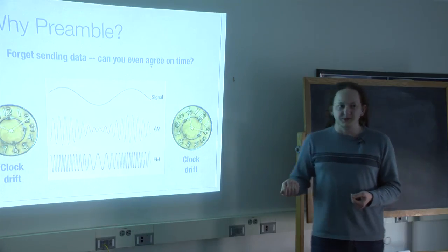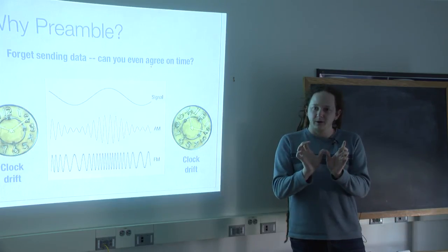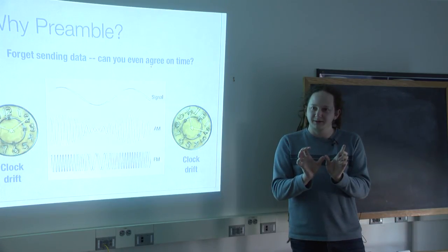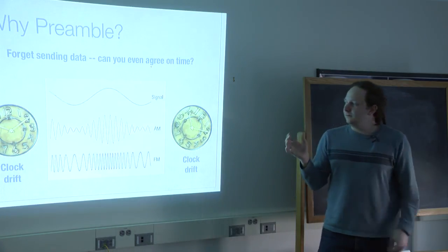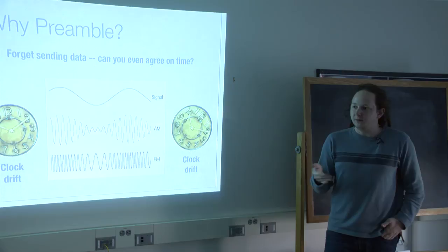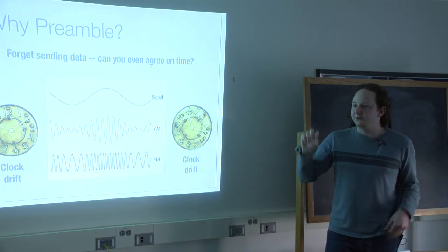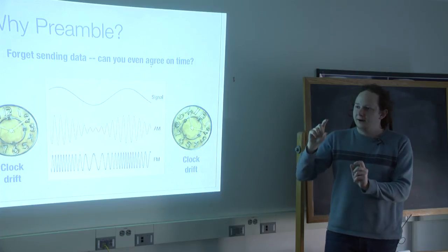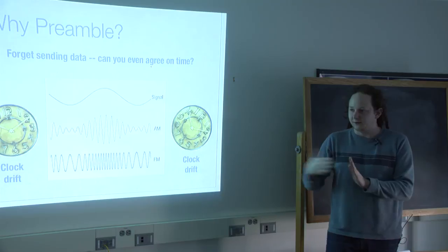The trick that they used was that they'd have a screech of very loud noise just before the start of frame delimiter in one of the modem packets. And then if you play it into an Apple II or a Commodore, which does not have automatic gain control, then it works fine because it's too loud during the meaningless part, and then the volume drops for the regular part, and you can still hear the packet.